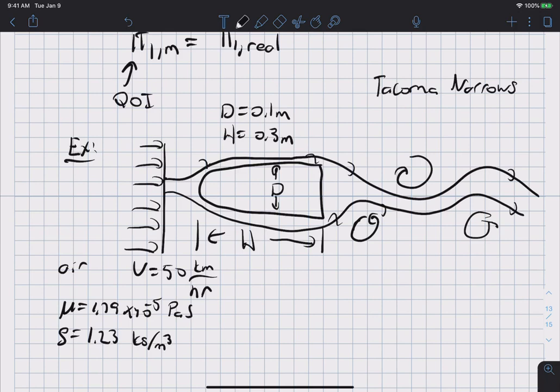Essentially what these vortexes do, and basically what this shaking set of streamlines does, is it applies a torque, it applies a shaking torque on the object. And if this frequency of these vortices is in the proper regime, this torque can become quite large, and it can couple with the bridge, set up a resonance, and you'll learn all about that when you take vibrations, and the bridge can literally shake itself apart, which you obviously don't want.